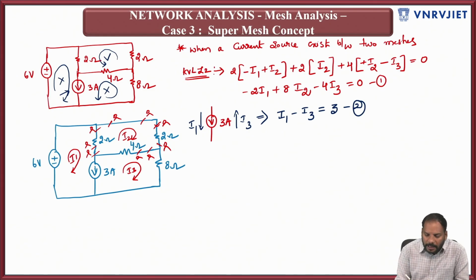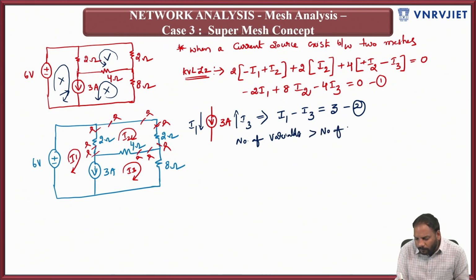The number of variables is greater than the number of equations, so apply the super mesh concept.